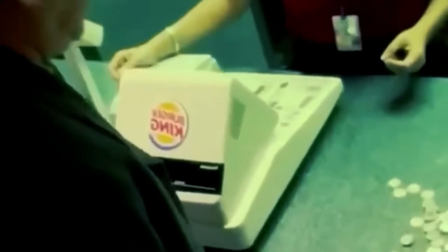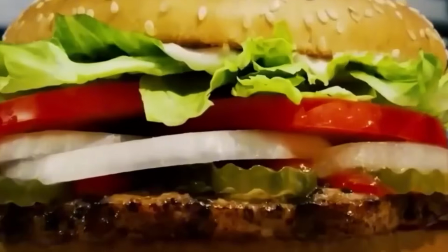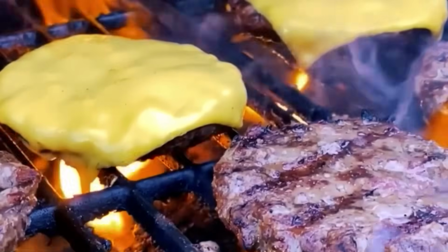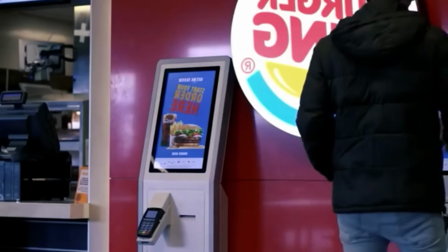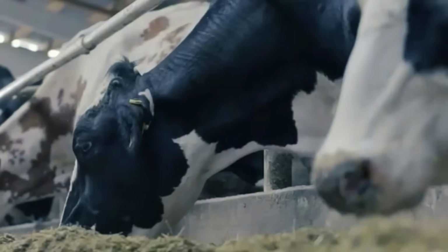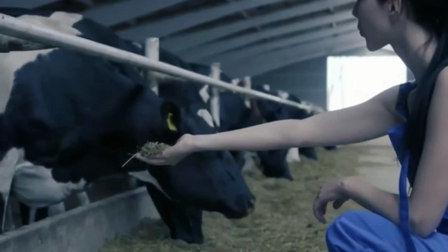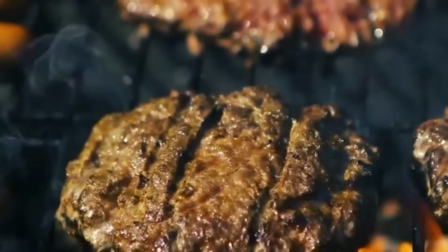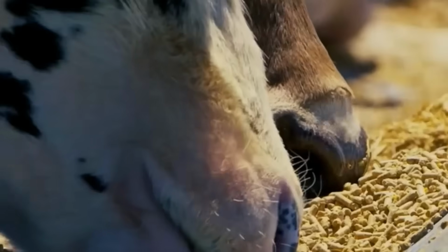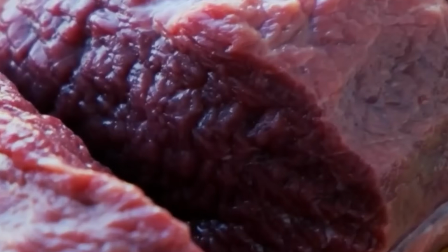As the patty enters the broiler tunnel, infrared sensors verify burner ignition and temperature stability. The open flame directly contacts the surface of the patty, inducing a Maillard reaction that produces characteristic grill marks and seared flavor. Simultaneously, moisture is driven out of the meat surface, concentrating the flavor and forming a firm exterior crust. The broiler conveyor moves at a calibrated pace, typically between 2.5 to 3.5 minutes per pass, depending on the product type.